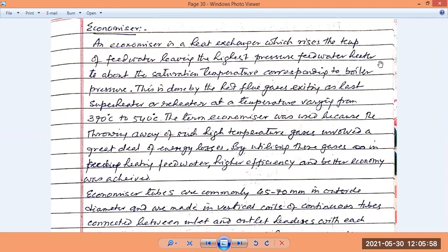In a boiler, we have furnaces where we put fuels like coal, and you have to feed air to supply oxygen along with it, so that there can be quick and reasonable burning. To ensure quick and reasonable burning, we heat the air in the preheater up to a temperature of 460 degrees centigrade, and then send it into the furnace. A portion of this preheated air is then sent to dry the coal before it is sent into the furnace itself.